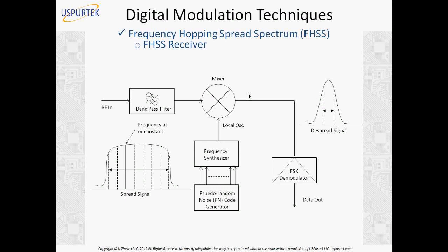So as I just said, with FHSS we cannot use QAM because of the incoherent phase from one frequency to another. Okay, there's a question: why not QAM again, please? So, in quadrature amplitude modulation, we have to maintain a very strict phase difference between I and Q signals. We have seen that before. So phase is very important. Phase coherence has to be maintained. The phase should not change actually. We have seen what phase noise can do.